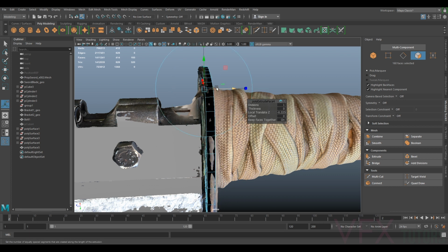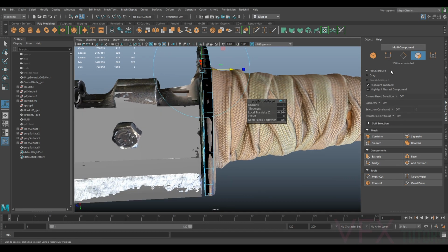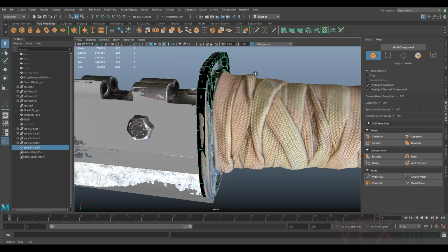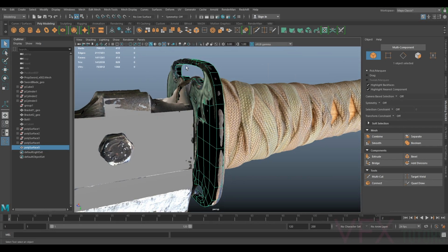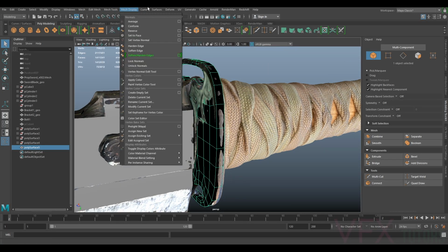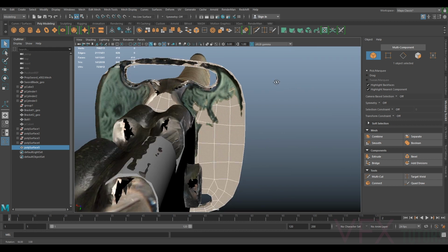because this might be something that you'll come across anyway, so I may as well show you how to fix this. Because no doubt at some point you'll end up with black polygons. So what's happened here is you've flipped the normals. So if we now go to our mesh tool, to mesh display and reverse, our normals are now flipped back.